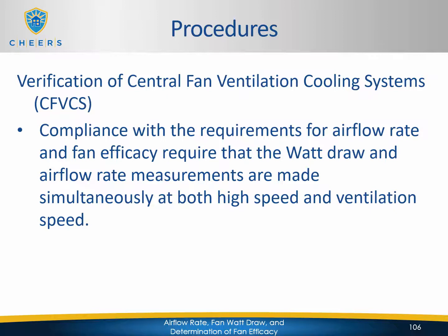And so it's going to bring cool outdoor air in, distribute it through the house, and it's going to cool using that instead of a mechanical means such as the compressor and AC system. So when you have one of these central fan ventilation cooling systems, it's going to be using the blower motor for that air handler. We're going to have to verify that the watt draw of that air handler meets or is better than the target value that we'll see when they model it.